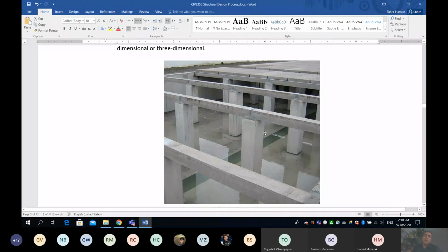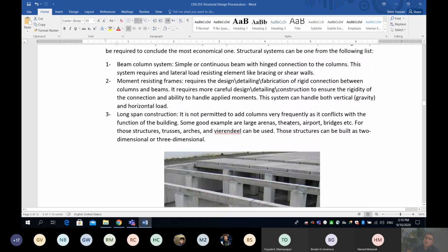So here is the trick. Probably I have to tell you which one I'm referring to. Look at where I'm pointing my cursor. What is this one? This is a joint. Simply, the joint in the beam discontinues your beam. If this joint is on every column, it means all of them are simple beams. If this joint doesn't exist, it means the beam is continuous on top of the column. Hopefully you know the difference between a simple beam and a continuous beam.